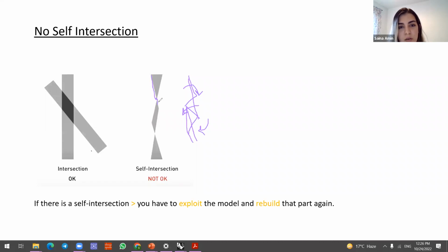So we should pay attention to the whole surfaces that we make. For example, we should think about the position of these points compared to each other. When we change the direction, we can see that one part of the surface is bright red and the other one is dark red. It's something that we should pay attention to. It's not a good thing, and it means surface intersections. Most of the time, you can see some errors or a window opening asking whether you are sure you want to do it or want to change direction. I think if you work with Rhino, you saw it already.